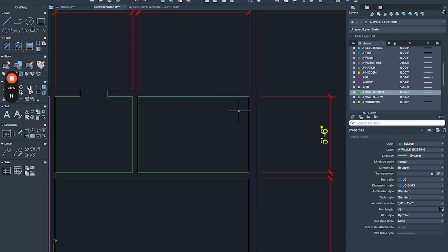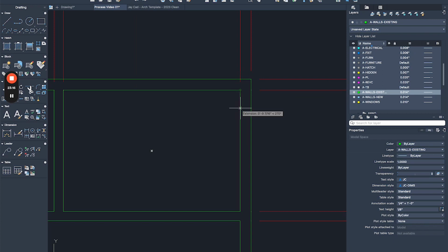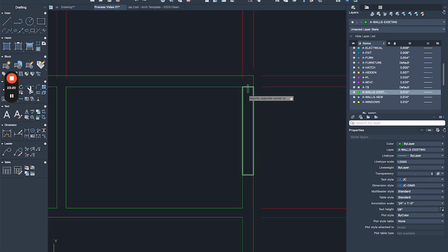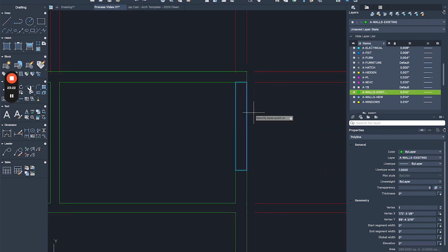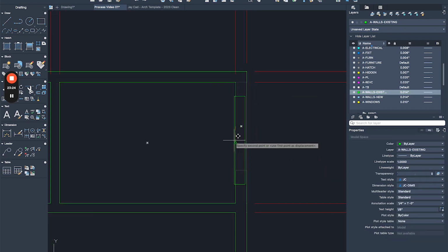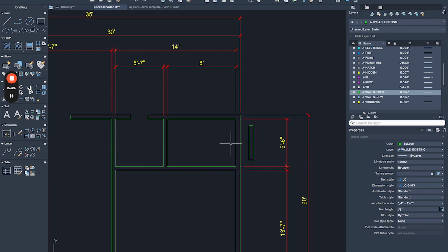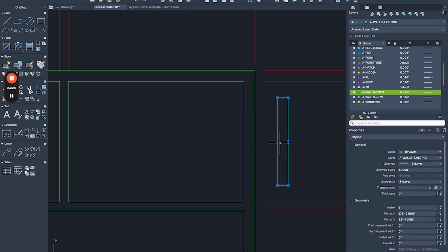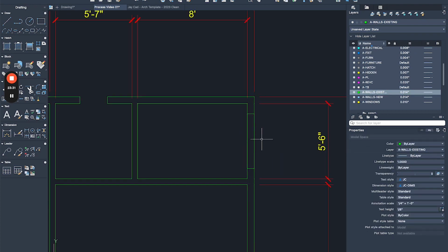And then here I'm gonna have the shower in this portion. So I'd like to add a window here. So I'll do the new process that I'm showing you. I'm gonna do 4 feet, then reference here. I have a polyline or rectangle essentially. I use the rectangle command. I know I have a snap point here in the middle, so I'm literally just referencing it like this. Then I'm trimming the whole thing, joining all of them. Okay, I needed to select once.